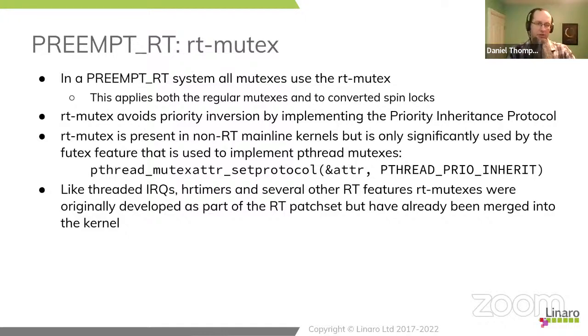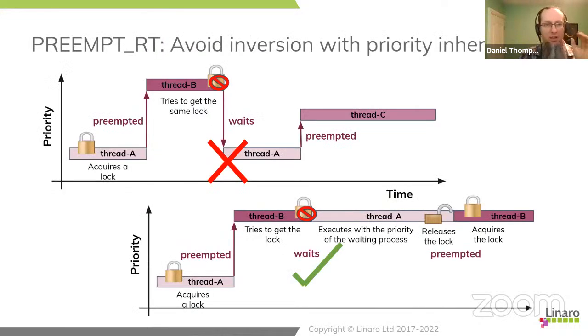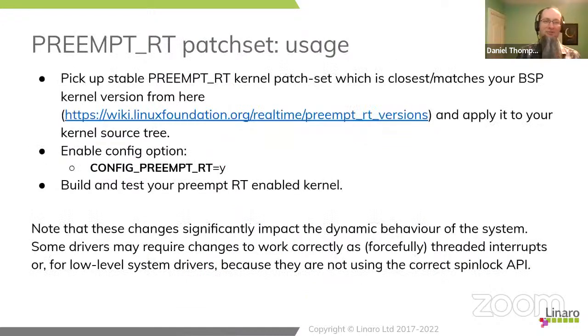So now we have hardly any time where we have to disable preemption. We've got priority inheritance, and we've got controllable interrupts that are prioritized. I think I won't speak to this slide. This is the same diagram you saw last week as an explanation of what priority inversion was. It's mostly useful for when I deliver this talk without the preceding module.